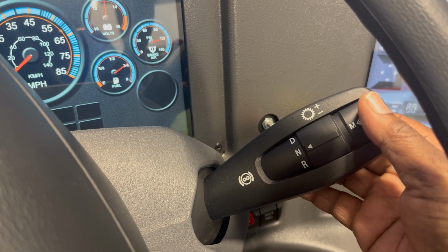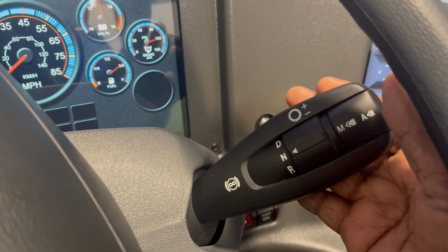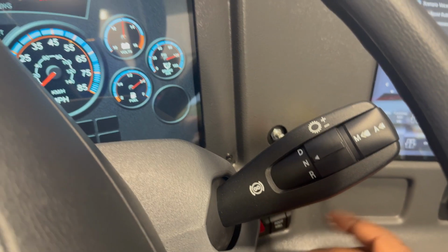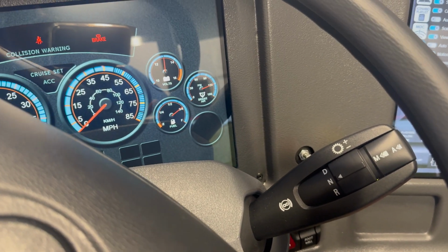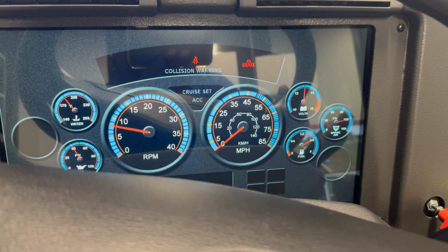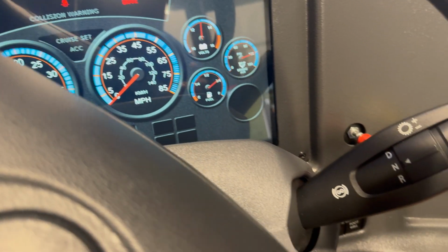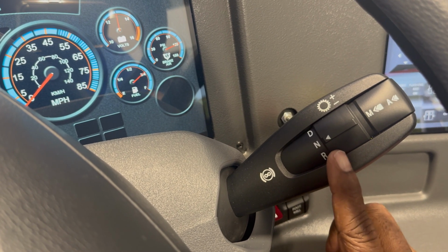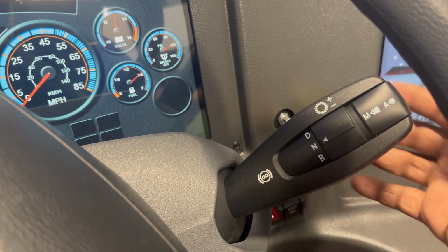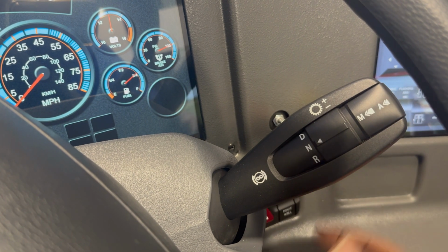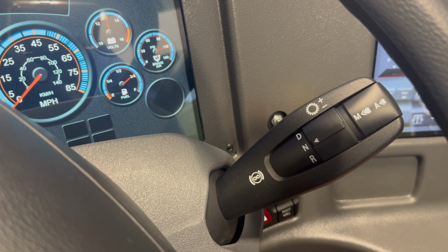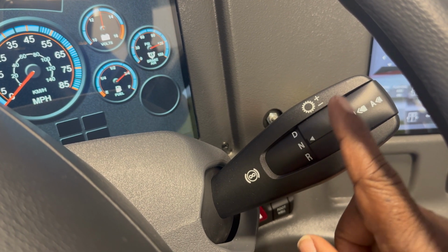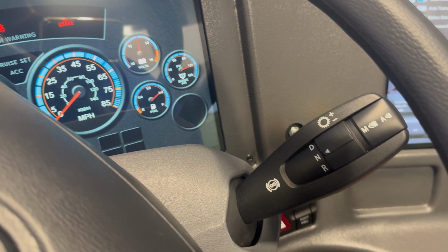And you should be able to know how to put it in the manual mode so you can manually shift the gears up or manually shift the gears down. So you guys need to come over to us, to KBC Transport, to get a refresher training on how to use this. I can actually put you on a mountain and let you come down a steep grade mountain and get proficient when it comes to using this. Because if you got 40,000 plus pounds on the back of that truck, you need to know how to utilize this auto shift transmission device, okay?